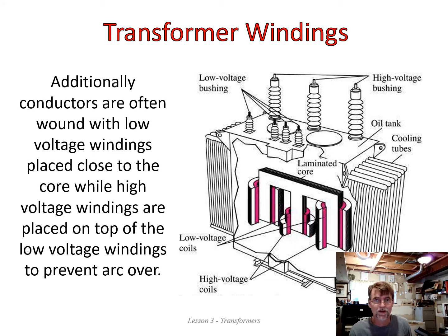Okay, if the two coils are identical, okay, then we call this an isolation transformer, and it doesn't change the voltage and the current. It stays the very same. Okay, it's called a 1-to-1 transformer, and the voltage in is the voltage out. Okay, if the two coils are the same.